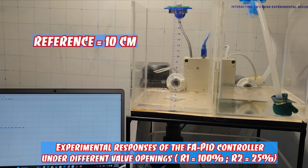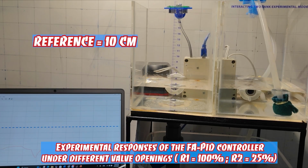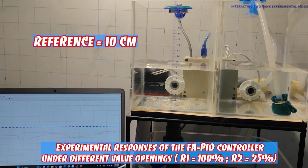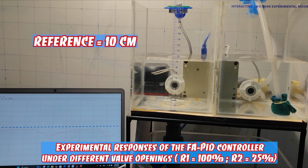Now we move to the experimental run. This part will be fast-forwarded for easier viewing. In the first experiment, we open valve R1 to 100% and valve R2 to 25% with the reference liquid levels set at 10 centimeters. As we can see, the response follows the reference level quite well with no overshoot occurring.